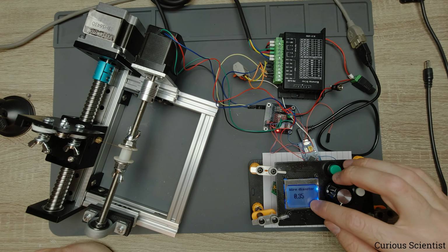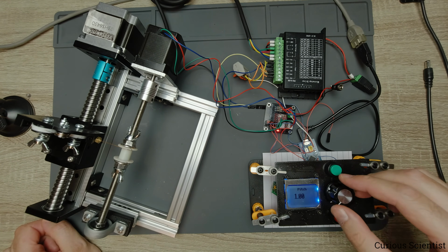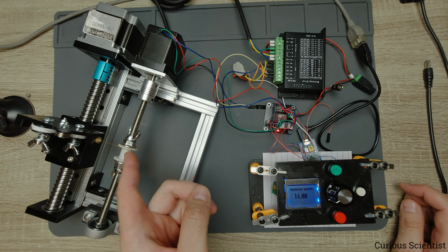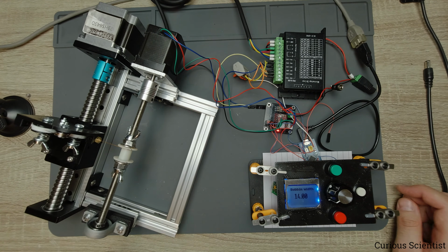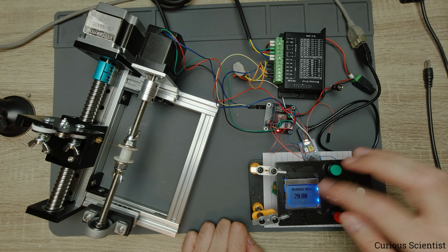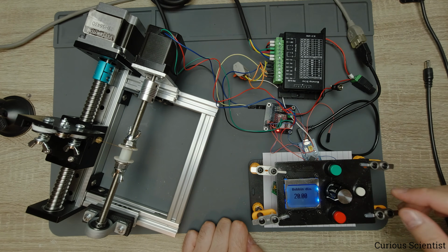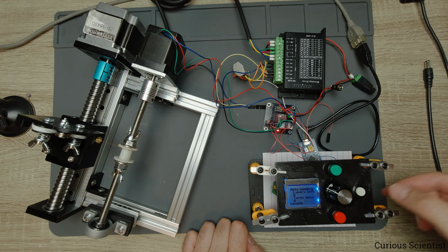And then 0.35 millimeter is the wire diameter. That's more or less fine, and the bobbin width is 14 millimeters. So that will define the, let's say, oscillation distance for the feeder. And the bobbin diameter is 2 centimeters, but that will just give us the information regarding the used wire length, so it's not really relevant.